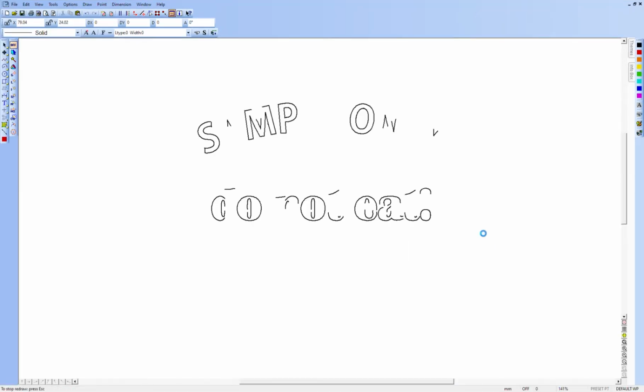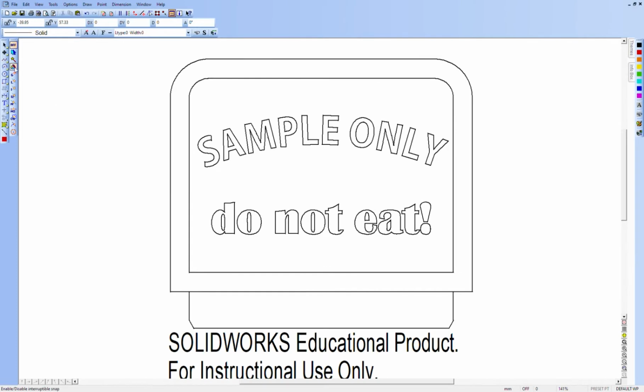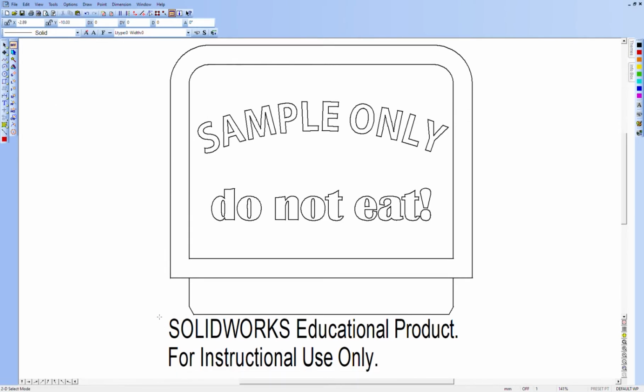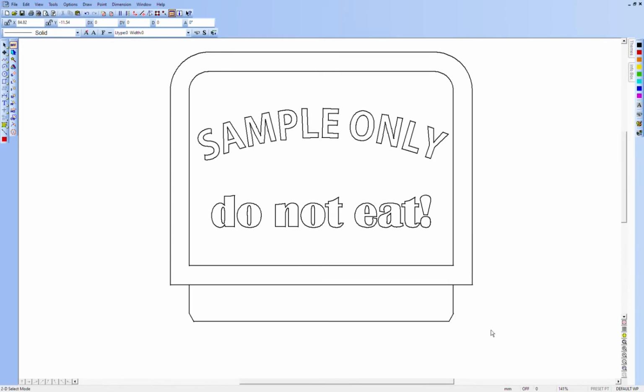The imported drawing will pop up on our screen in DesignCAD. We can see that there's a watermark there, reminding us that we're using a non-commercial version of SOLIDWORKS. So we'll just drop a box around the watermark to select it all. Alternatively, we can select either the top line or bottom line of the text just by clicking on them. Press the Delete key. To zoom out a little bit here, we'll press the minus key.